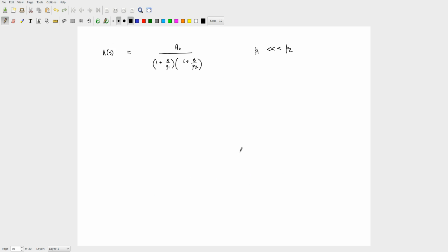Okay. So, how will this transfer function actually look? We drew it, right. So, it will be flat till some small value, then minus 20 dB per decade, and then minus 40 dB per decade. And what will P1 and P2 be? This will be P1. I am using P1 and omega P1 interchangeably, be careful, it is all the same stuff. P1 is the pole, it may have a negative sign, but I am taking the magnitude.